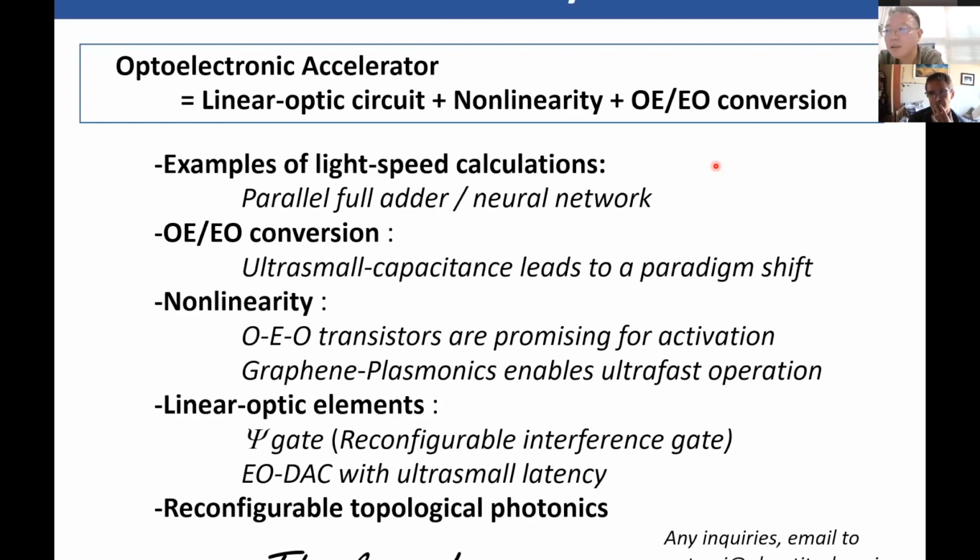I don't think so. For example, in our case, the capacitance is almost comparable to the capacitance of a CMOS gate. If we simply compare the wavelengths of electrons and photons, there are probably 2 or 3 orders of magnitude difference. But for the capacitance, there is no such big gap, because the capacitance is determined by the configuration of the two electric plates. So there is more freedom for making the size smaller.